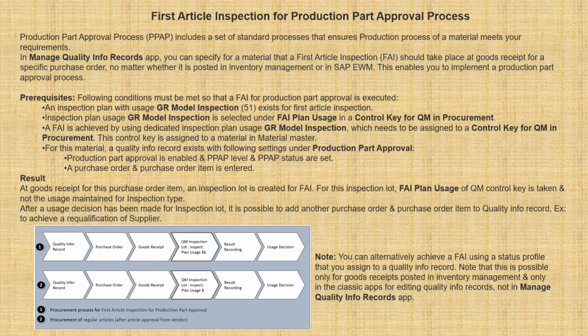If it is, say, any manufacturing company where they are manufacturing some article, when they produce their first piece, or the first article, they inspect it. We call it first article inspection because we inspect the first article which is produced or manufactured using the same production process which will be used for the mass production of that same material.